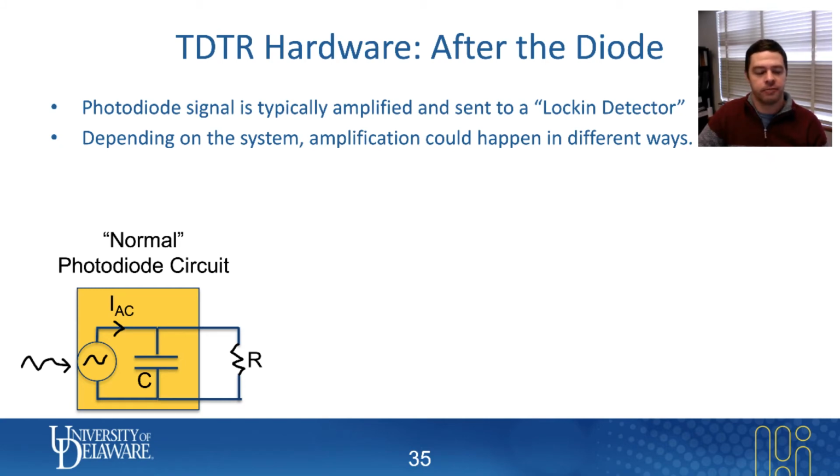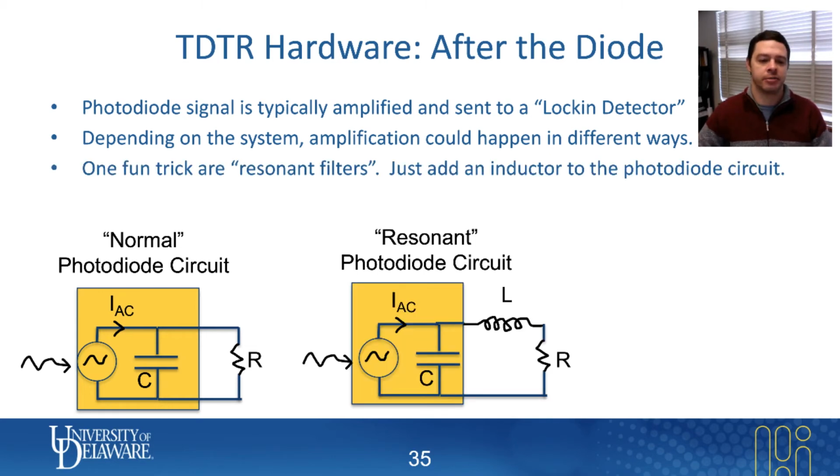but it is finite. Then externally, what you actually see when you operate these things is basically a BNC cable connection, which is the connection that you'll use to send the signal to either your lock-in amplifier or to a preamplifier if you're using one. Inside either the lock-in amplifier or the preamplifier, across the two terminals, there's usually a 50 ohm resistor that you're passing the photodiode circuit through. Okay, so that's basically how a normal photodiode circuit works. I'm sort of hiding the biasing, but this is a good way to think about it.